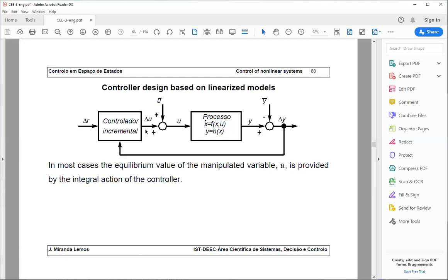So what is negative is the increment, but since the increment is added to the equilibrium points, there is no saturation at 0. And the same thing here, okay? One thing also that you should notice is that usually this y bar is incorporated or added to delta R to build the full reference that compares. If you add delta R with y bar, it's a reference that compares to y, to the full signal y.